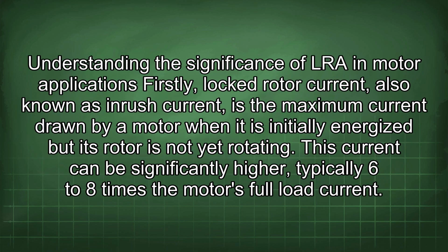Understanding the significance of LRA in motor applications. Firstly, locked rotor current, also known as inrush current, is the maximum current drawn by a motor when it is initially energized but its rotor is not yet rotating. This current can be significantly higher, typically 6 to 8 times the motor's full load current.